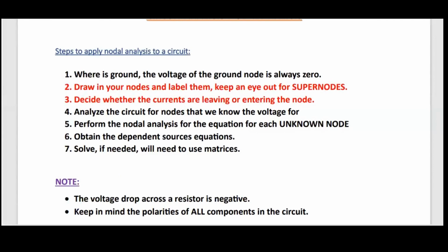All right, so the two techniques you can use to get those currents and voltages are called nodal analysis and loop analysis. This here is nodal analysis. Basically, the first thing you need to do is label nodes. That's literally the whole technique. You need nodes. Before I start, these are the steps within the notes. You need to go through these steps, and I'll go through them with you. Anytime you look at a circuit, these are the steps you'll go through.